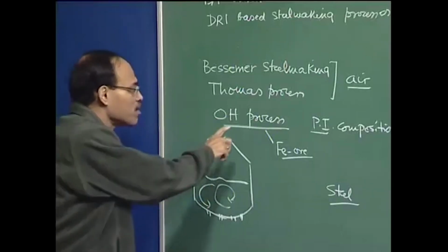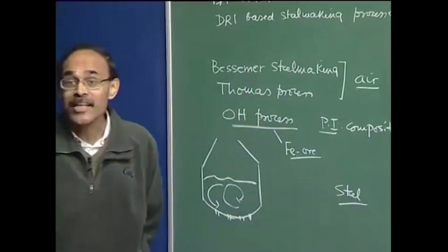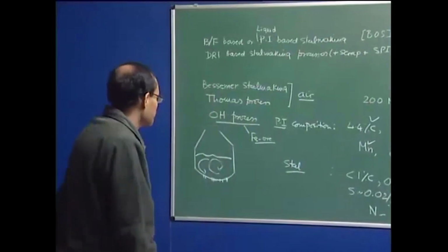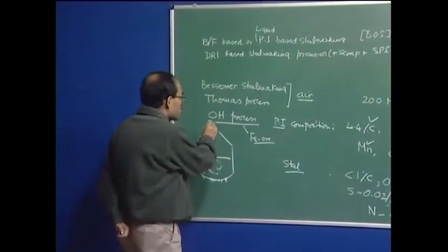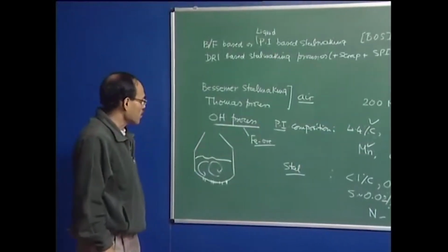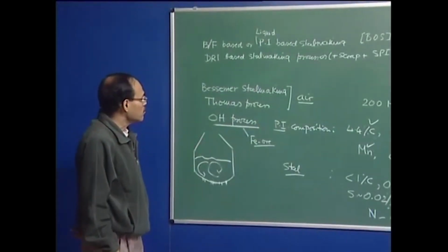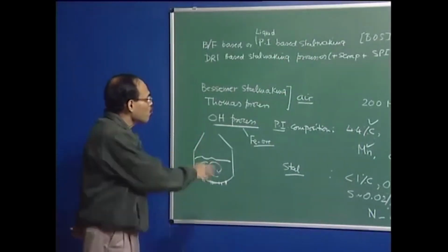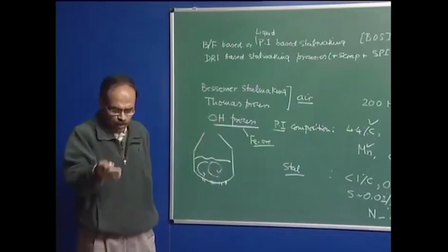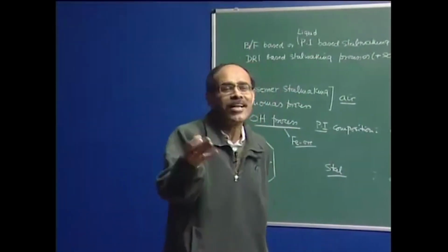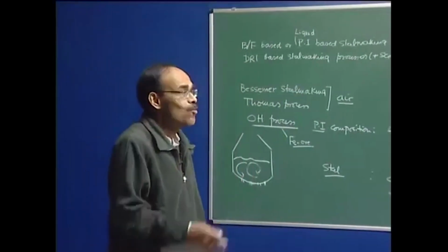But because the level of agitation in the open hearth process is small, the rate of steel production is extremely weak. So, the relatively slow rate of the open hearth process is responsible for its loss of popularity, and therefore later versions of open hearth processes involve some kind of oxygen lancing also. But today, with oxygen steel making processes, we are better off.